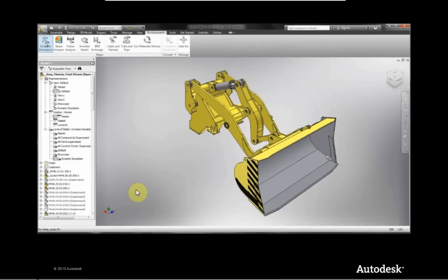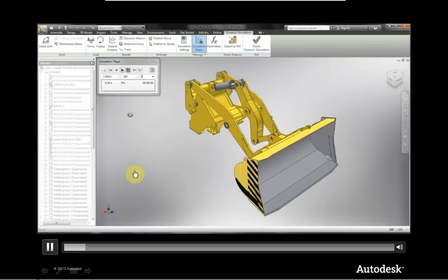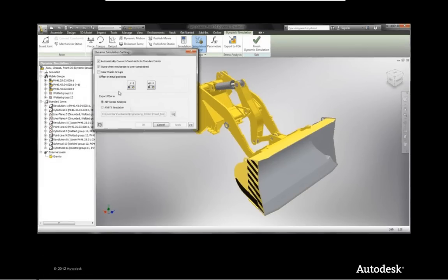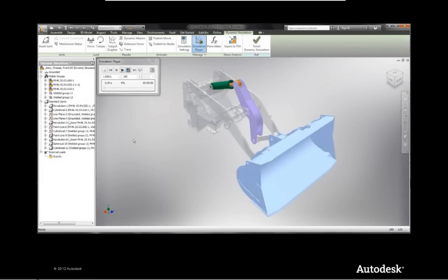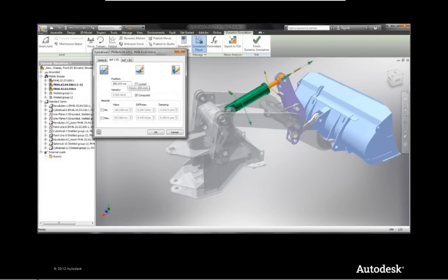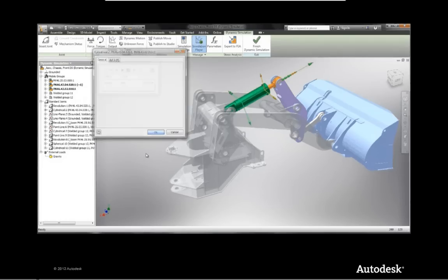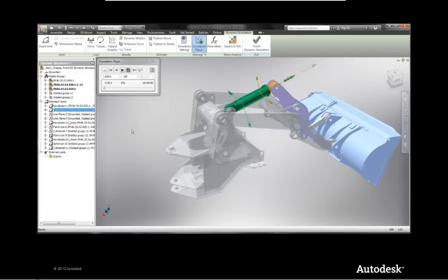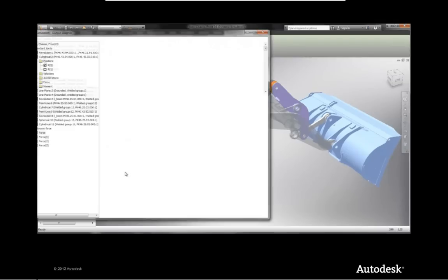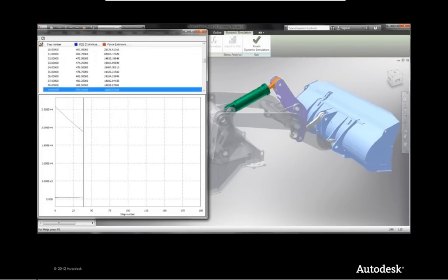In the Inventor Professional, you've got the dynamic simulation product. This is a little underutilized, in my opinion. It enables you to actually design real-world mechanisms with springs and dampers and joints that you would expect to have in the real world, and apply friction and motion and torque and so on and so forth. And then produce a mechanism analysis of this design, and also send these forces that are experienced within the design across to an FEA package to then run a stress analysis.